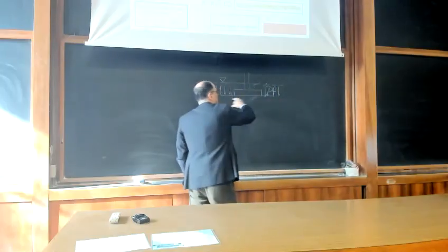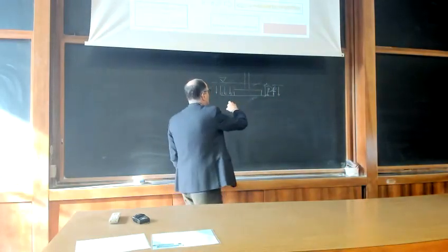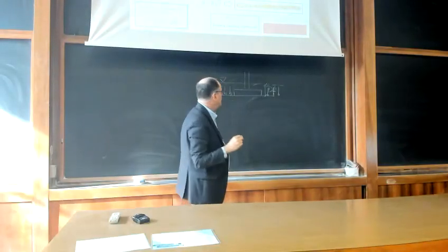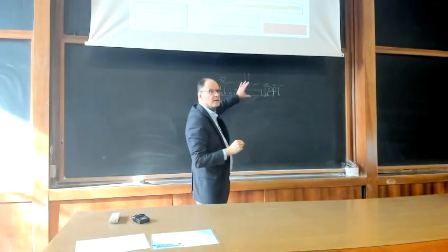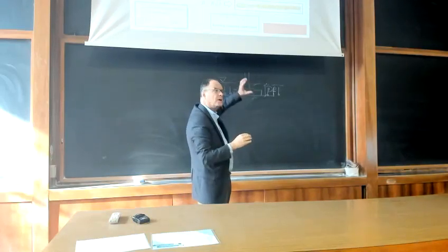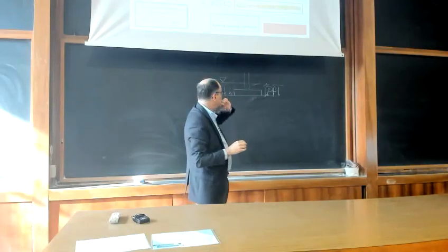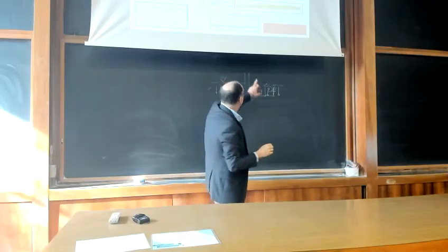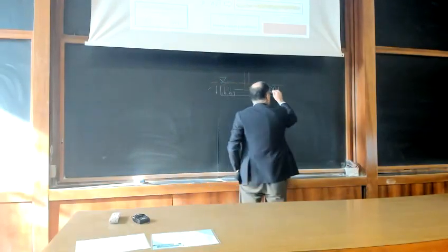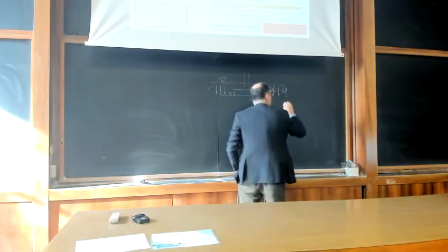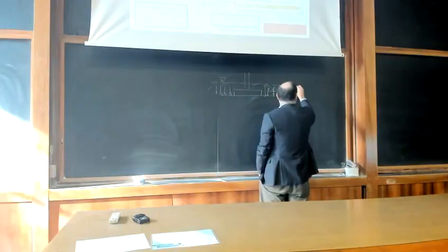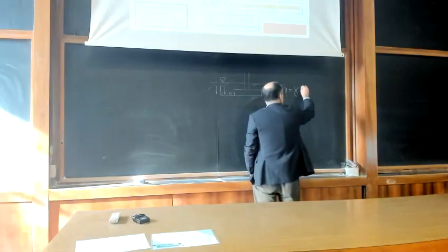Okay, so we can build a scheme in which there is no soil above the foundation level, but of course, since there will be some soil, and that soil provides an important stress contribution, we, as you see on top, substitute this soil with its overburden contribution, which is Q equals gamma, the gamma of this soil, times DF.